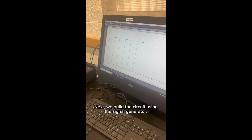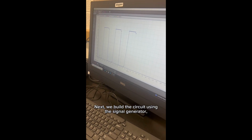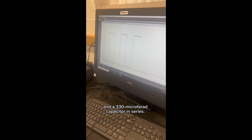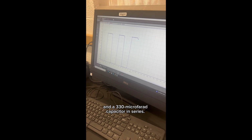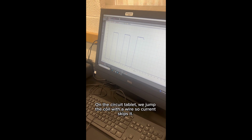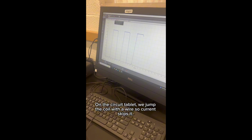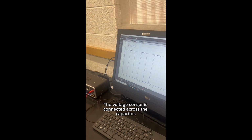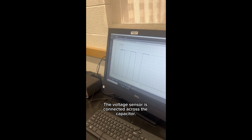Next, we build the circuit using the signal generator, a 10 ohm resistor, and a 330 microfarad capacitor in series. On the circuit tablet, we jump the coil with a wire so current skips it. The voltage sensor is connected across the capacitor.